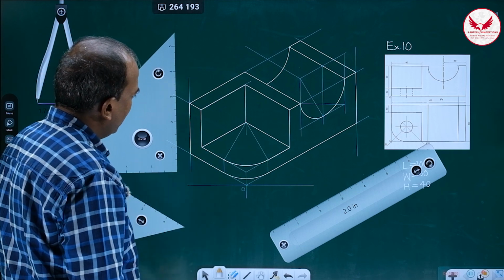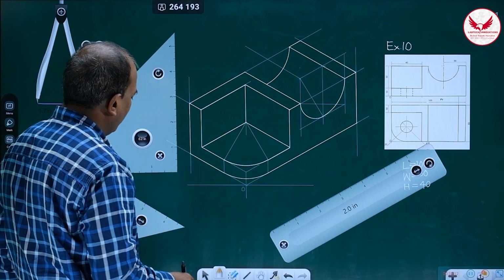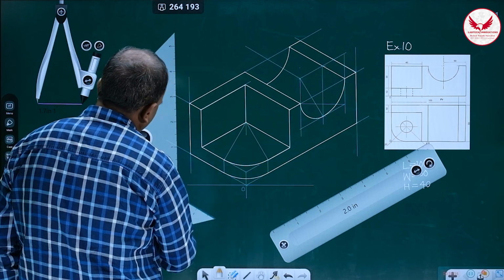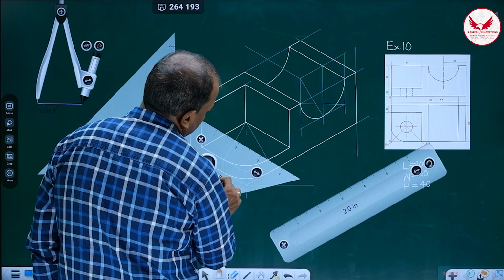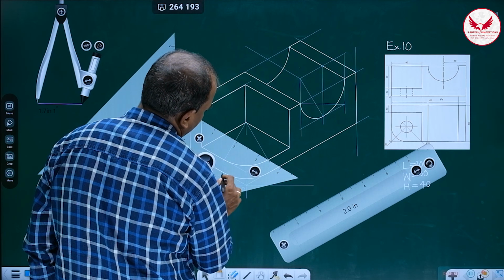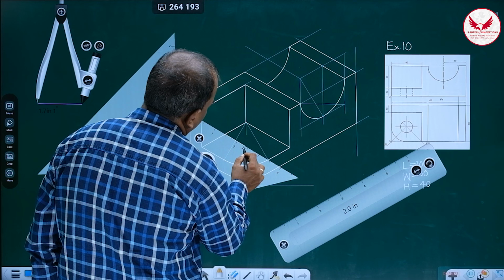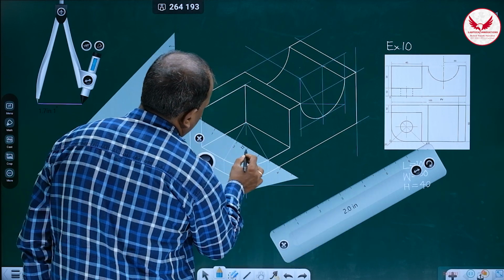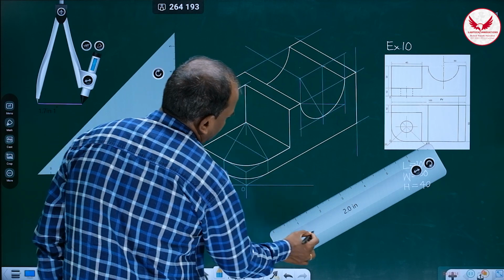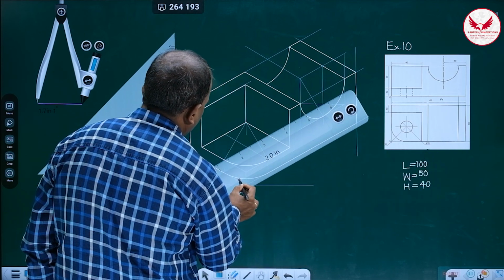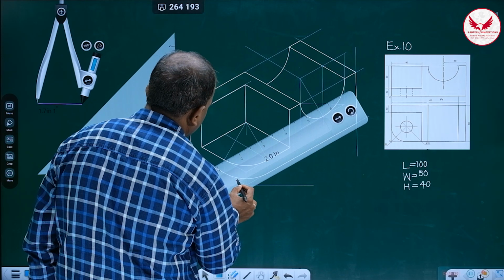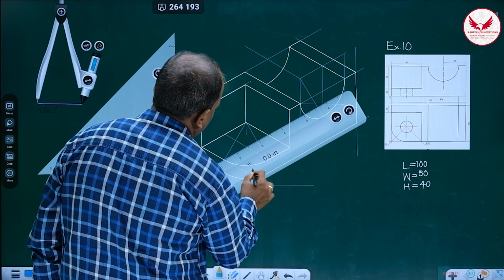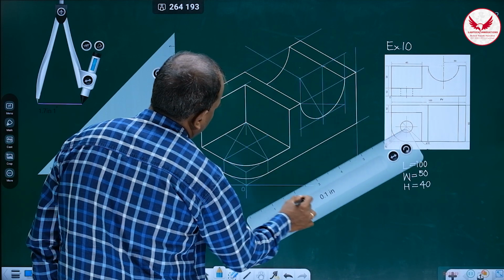that circular hole. For that, again we know, we have to draw the rhombus in the foreshortened method. Coincidentally, we have the midpoints of these sides over here. So mark the center. How can we mark the center over here? Draw this parallel line, and through this midpoint, a parallel line on this side. This is the center.